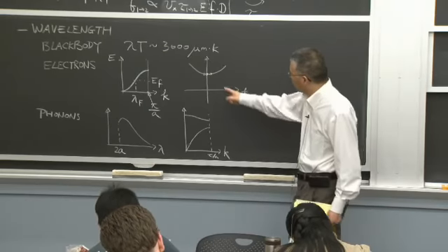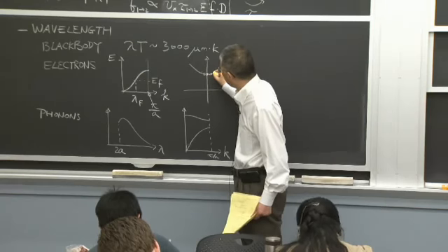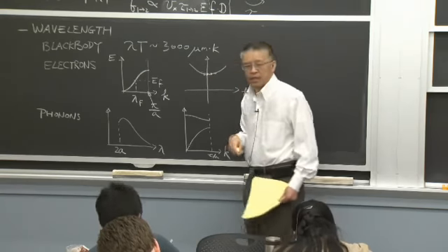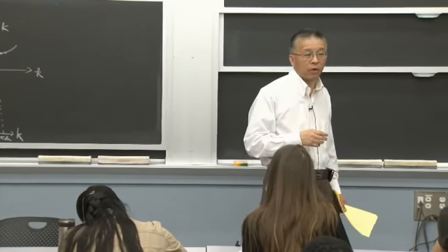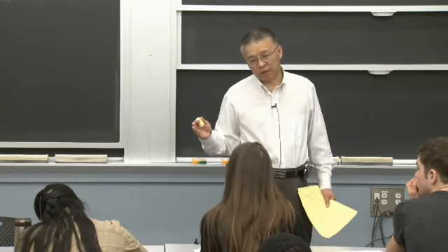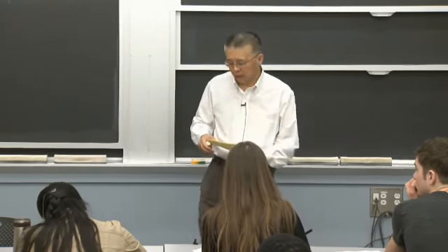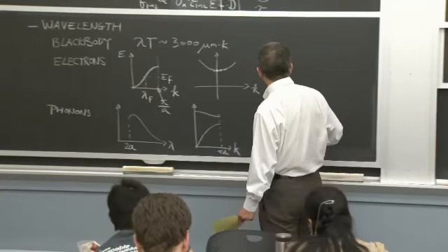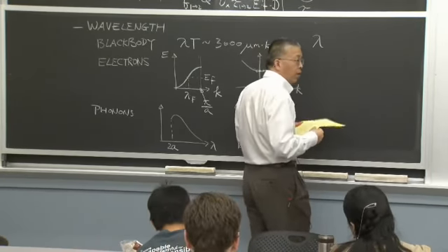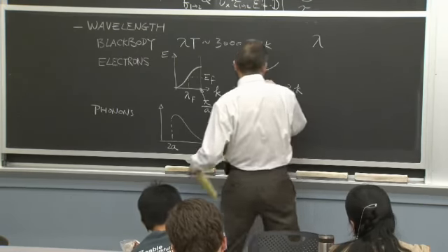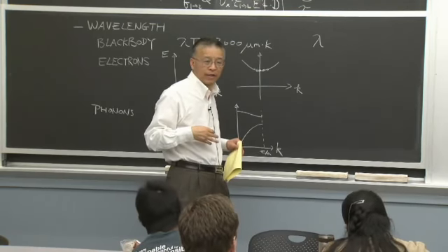And if I look at semiconductors, say this is the valence band, and most of the electrons are at the bottom of the valence band. So that's near k equals 0. And those electrons could have very long wavelengths. And in fact, in the last lecture, we talked about the de Broglie wavelength. So that's the thermal, if I have a thermal energy, kT, say the average energy is kT of the electron kinetic energy.